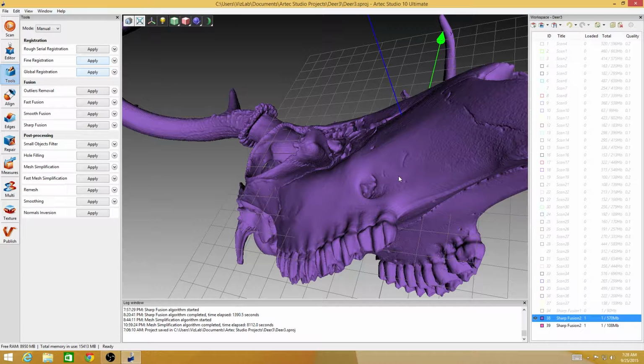But it is challenging in terms of being able to get all of the surfaces, the glossy surfaces, the tiny little nooks and crannies and all the little cavities, and understand that there's some things that you're just never going to get. So I went ahead and finished scanning in the antlers. The second antler went just like the first one. The biggest challenge with the antlers is positioning them so that you can get a good scan and keep tracking while you're getting down to the very ends of the tips. The isolated narrow geometry is a challenging surface to scan as well.